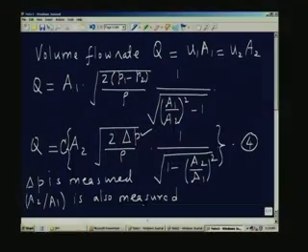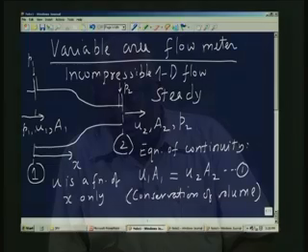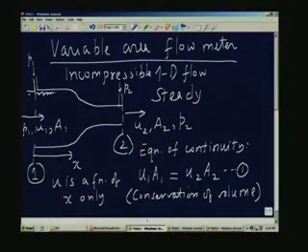Before we take a look at this, let me just clarify some points. In writing the equation, I wrote down the pressure as P1 here. I also wrote the pressure as P2 here. The question is, what we are going to do in practice is to measure the pressure at the wall, and here we are going to measure the pressure P2 at the wall. Okay. If there is some viscous effect, the viscous effect is going to be confined to the region close to the boundary.